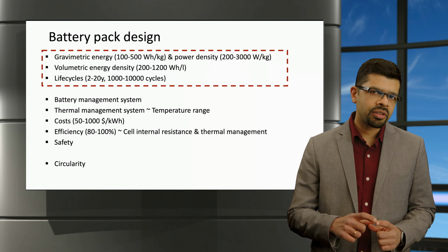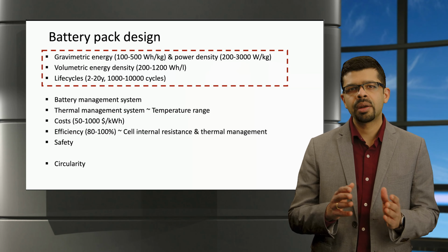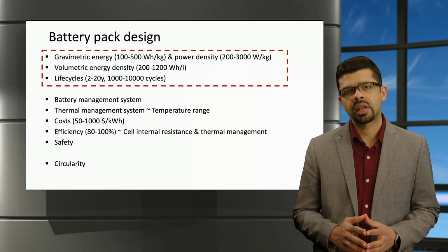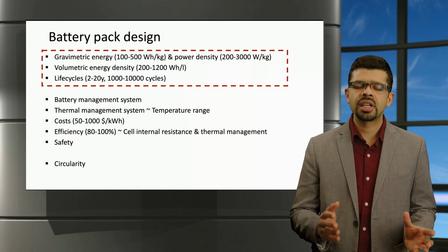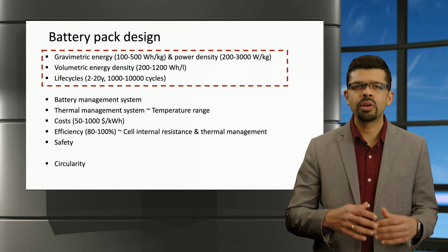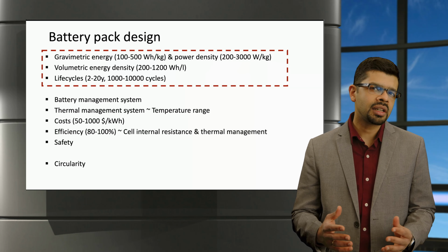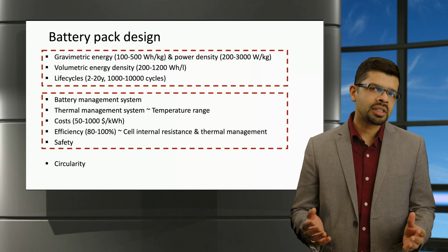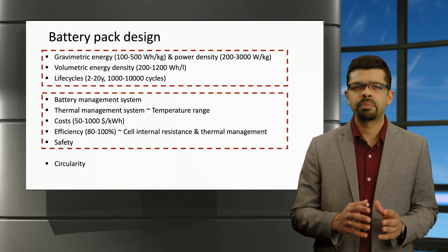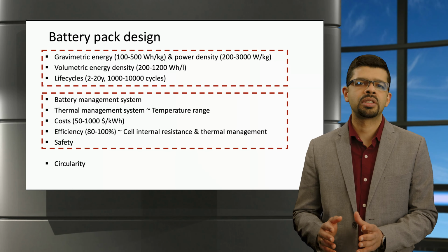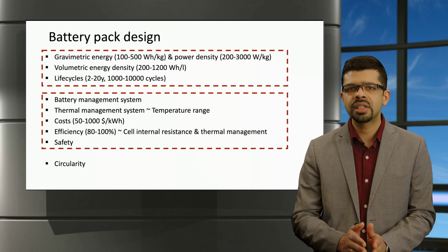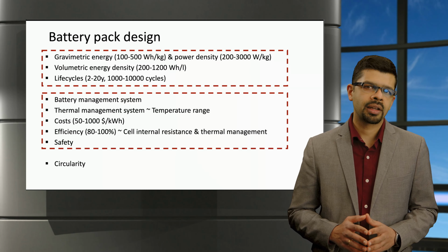At the cell level, we need to consider the gravimetric energy and power densities, and at times also the volumetric energy density of the cell. The lifetime of the cells in terms of both time and number of cycles is critical and depends on the application. At the pack level, the key design considerations are the battery management and thermal management system, which effectively influences the cost, efficiency, and the safety of the battery pack.